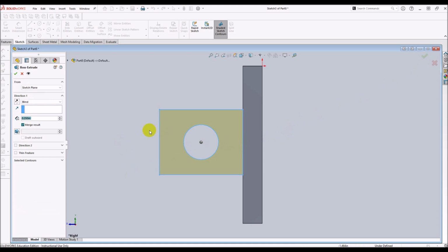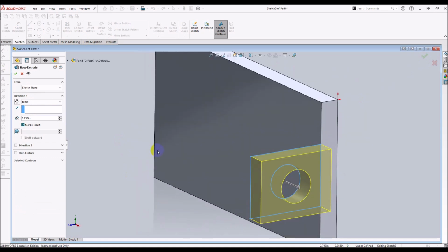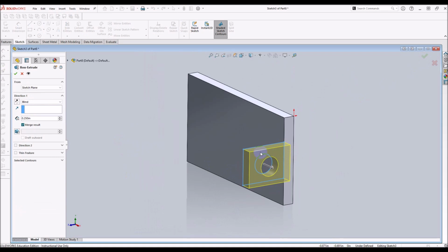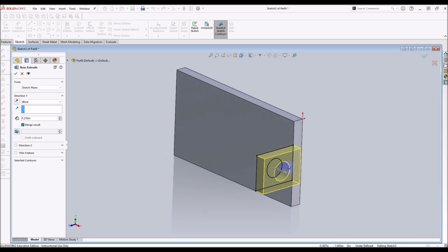If you press and hold the mouse wheel while moving the mouse to rotate the view slightly so we can see what's really going on, we can roll the wheel to zoom in or out. Right away we see that the direction of the extrude is inconvenient at best, but in fact what we really want is to extrude up to a selected surface.